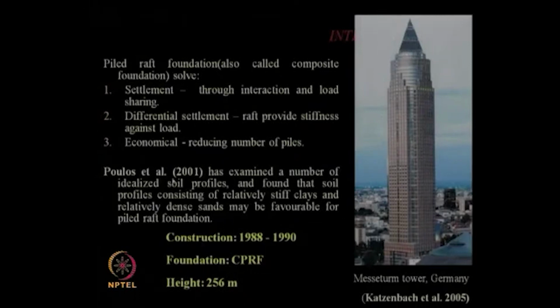Then Poulos et al. in 2001, he and his research group, also explained a number of idealized soil profiles and found that a soil profile consisting of relatively stiff clays and relatively dense sand may be favorable for pile raft foundation. You should remember there are conditions required for CPRF. It is not that in all cases you can use CPRF. There is a particular ratio of the stiffness of the soil layers from the raft level to the pile bottom level. It should be within some range, and only then can you apply this combined pile raft condition.